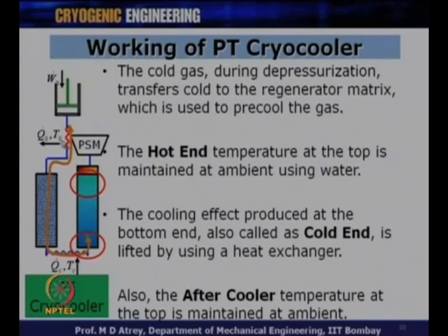So, you have an after cooler heat exchanger here, which maintains the temperature of the gas at ambient temperature. So, when the gas gets compressed, the gas enters the regenerator at ambient temperature because of the after cooling.